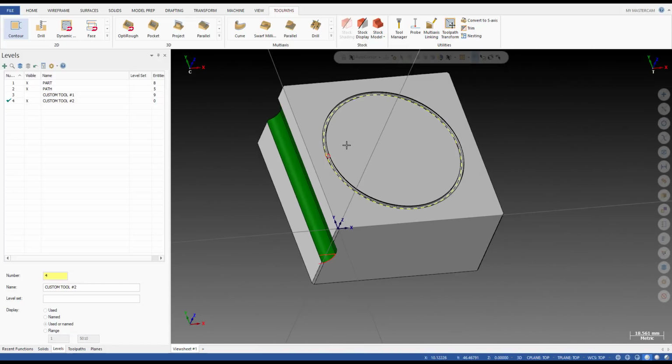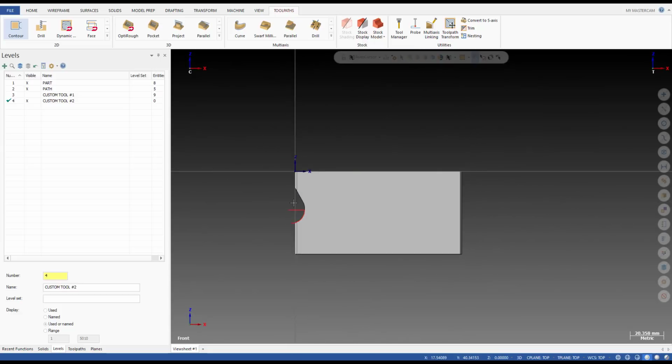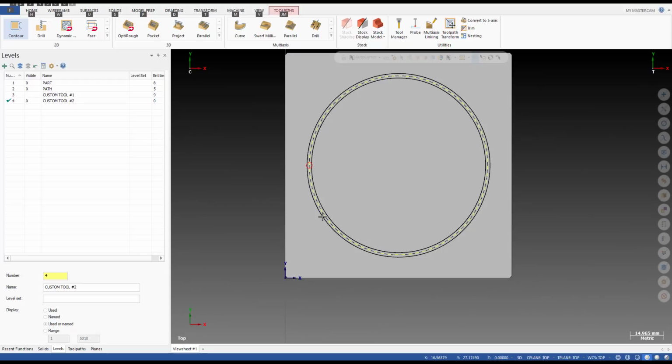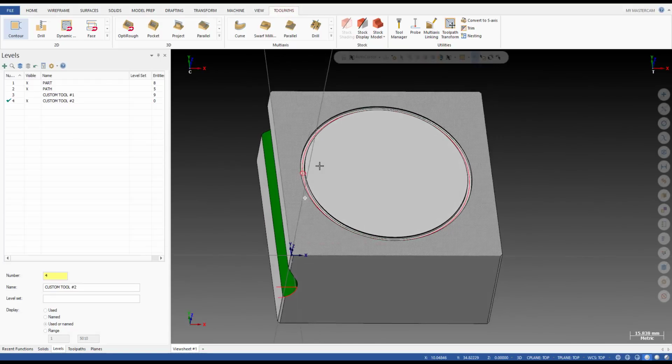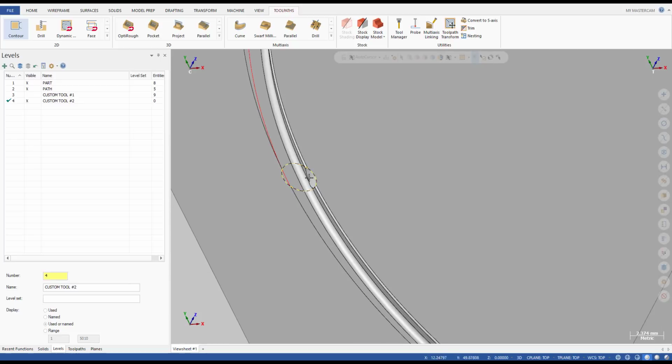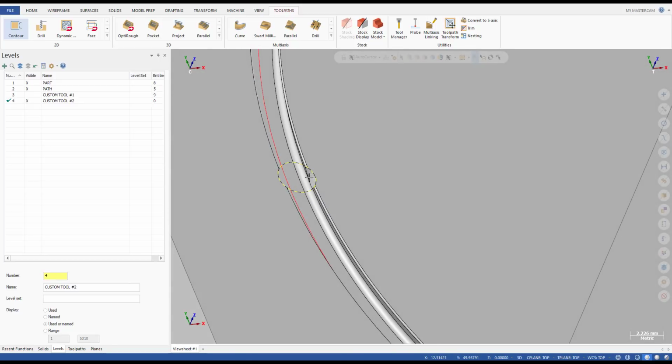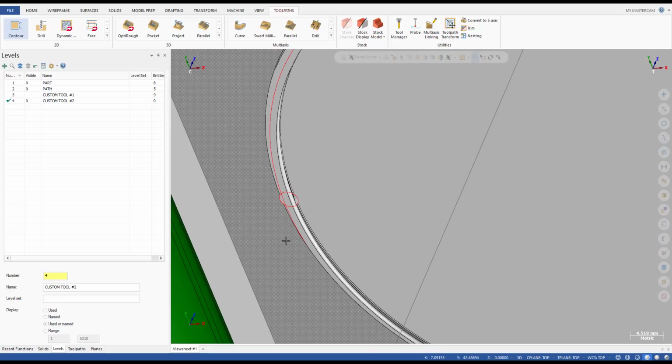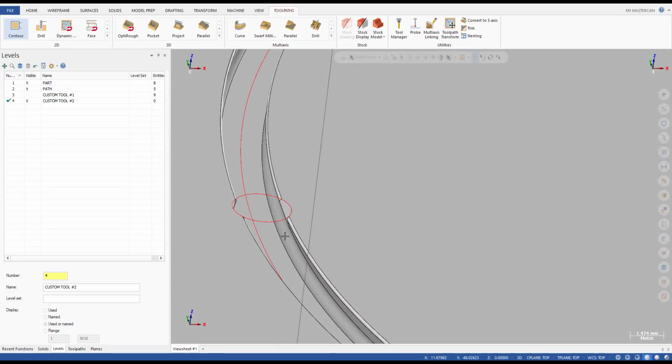We still add the first method, where we draw the tool profile and start it in a level. But with some geometry on the part, there is some standard, and if it is standard, you have the standard tool, and you can download the tool geometry from the manufacturing site. For example, I have an o-ring groove here, and this groove has a standard, maybe a standard of a company.